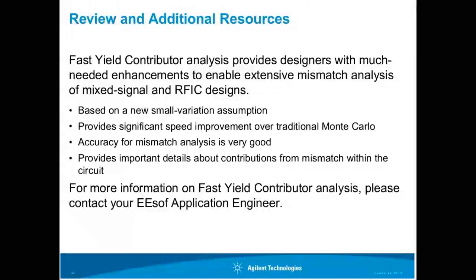Great. Thanks, Carmina. Thanks, George. That's a great overview. We do have a number of questions. One question I think I'll take myself was about the PDKs, especially for older or special technologies, embedded flash and whatnot, where the statistical models aren't available. Yes, the requirement for this technique, whether process Monte Carlo or process mismatch, is that you do need to have a statistical model available.